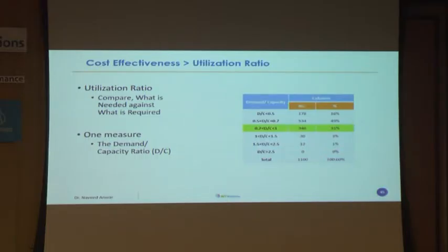Mostly we get much less, 0.3, 0.4. If the capacity ratio becomes more than 0.7, that means you're too close to the limits, and some members may be threatened by exceeding the demand capacity ratios. So we are looking at that optimum level of about 70% overall on the structure. Anything below is not efficient, not cost effective, it's a waste of resources. Anything above may be too close to the limits.